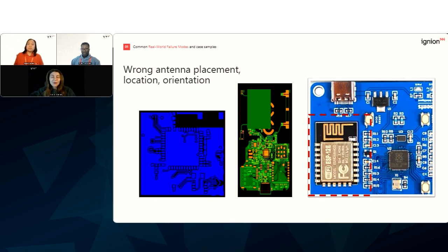Yeah, it's very often. It's one of the most popular problems, I would say, that the antenna enters the project at a very late stage. When we already don't have much space on the PCB, we have only some bad real estate left, and we just think, okay, we will put the antenna there and it will be okay. But it will not actually. Antenna depends a lot on different things, especially on the position, the surroundings, and the environment. So we really need to think about the antenna first.